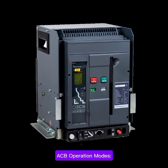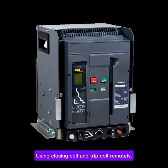ACB operation modes. ACB can be operated by manual operation using ON, OFF push button. Electrical operation using closing coil and trip coil remotely. Used in automation systems, PLC, ATS panels.